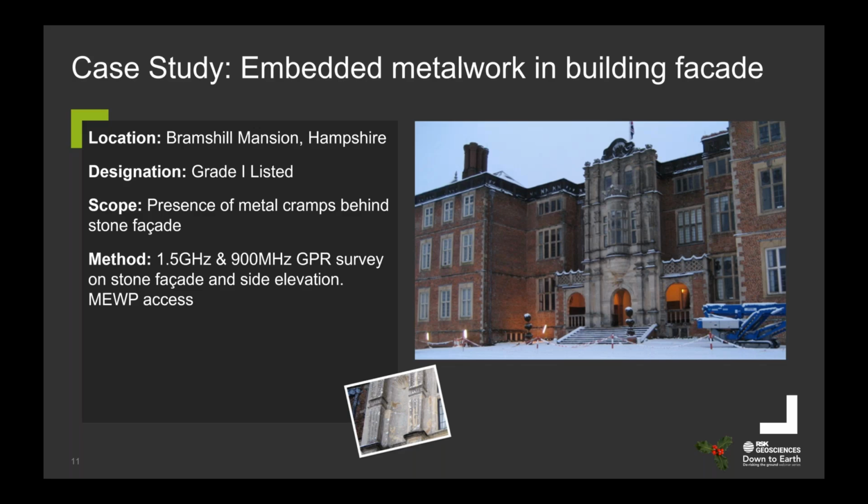Access was tricky. We had to use a mobile elevated working platform, which you can see in the bottom right of the image. And as is also the issue for listed buildings, there's lots of areas of intricate stonework, and this can limit the GPR survey locations. We used two frequencies of high frequency radar in order to get the detail that we needed of the metalwork, as it's usually quite small in scale.